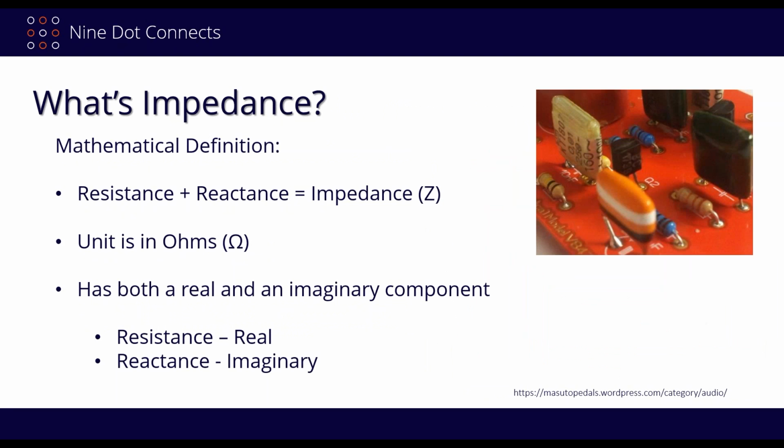Well, first and foremost, let's spend a few moments to talk about impedance itself, just a quick refresher. It's made of resistance and reactance, and its units are in ohms. Now, most of us like the resistance part of it because it's constant. Regardless of the frequency, it's always going to remain the same. It's the reactance part that gets us tripped up. So let's take a brief look at that. Just keep in mind that the reactance is what they call the imaginary part of the impedance. I always got a kick out of that name, imaginary, because it's very real. There's something very real happening with the signal over here, so I don't know how I can possibly imagine it. But the mathematicians call it imaginary, so we'll have to stick with that.